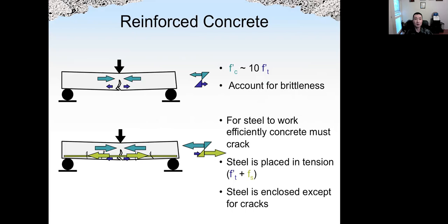And here shows why we should put reinforcement or rebar in a concrete specimen. If the concrete beam, in this case, has no steel rebar, because concrete is very weak under tension, the bottom tends to crack earlier under this load. If we put steel rebar in the areas where the concrete will experience tension load, the rebar will take most of the tension load. As a result, the reinforced concrete beam will take much more moment compared with the plain beam.